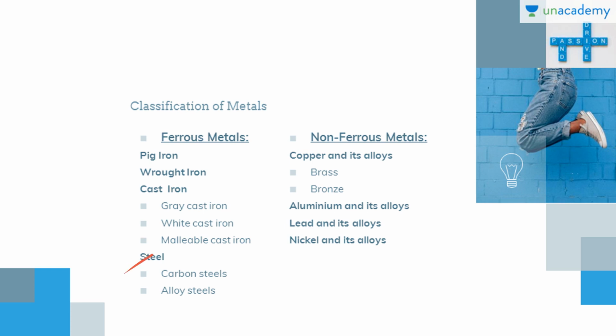Steel is an alloy of iron and carbon, with carbon content being less than 2%. In addition, various alloying elements like sulfur, phosphorus and manganese are added in small proportions to obtain the desired properties in steel. Coming to the low carbon steel, it is also called mild steel, which is the common type of carbon steel and contains about 0.03 to 0.25% of carbon. Whereas medium carbon steels contain carbon in the range of 0.25 to 0.59%. And high carbon steels contain increased carbon content, in the range of 0.6%.